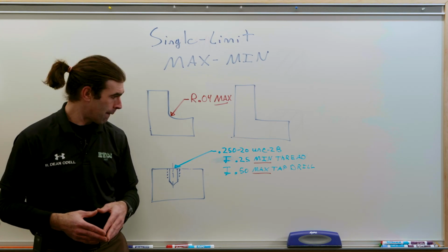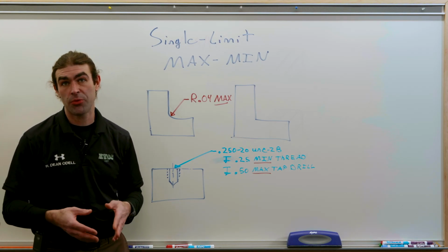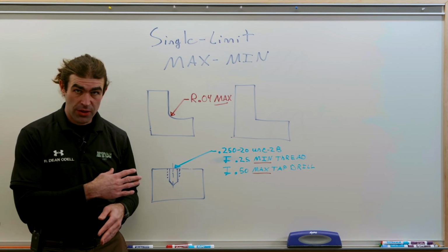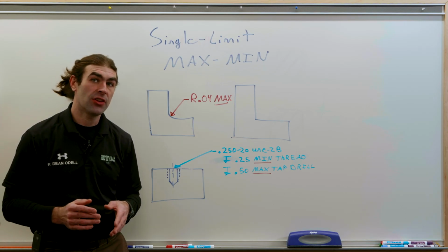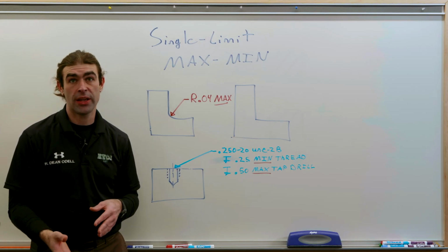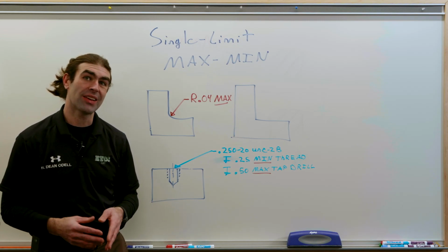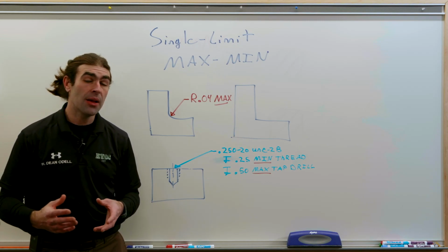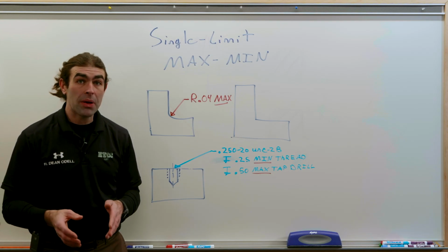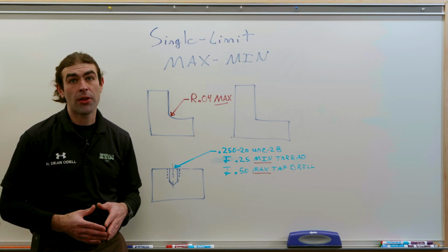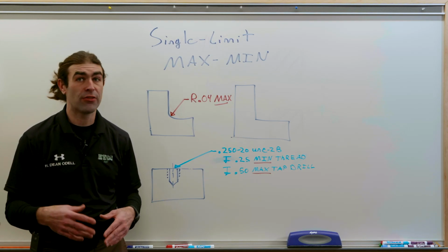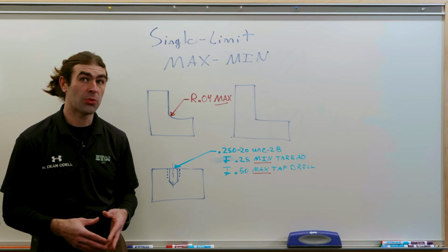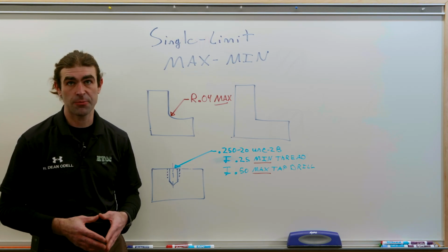So max tap drill. So you could conceivably have a 1/2 inch deep thread, but it couldn't go any further. So these two tolerances kind of limit each other. Again, this is easier to inspect than specifying 1/2 inch plus or minus 10 thousandths, or leaving it to go to a title block tolerance where it might be even tighter than that.